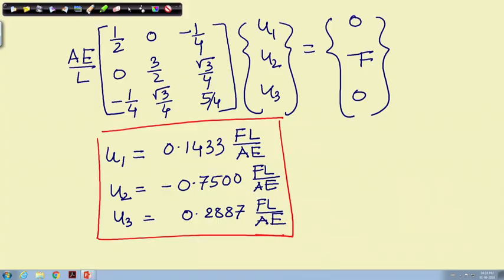So, please note, the partition of the stiffness matrix is a very important step, and we can demonstrate only the process through one or two examples at the most. If you look at books, there are many examples given with different numbering, different boundary conditions, different numbers of members. You yourself try to find out the member stiffness matrices, assemble them, and then construct the load vector and the displacement vector and solve them. If you can do that, then probably some of the concepts will be clear.